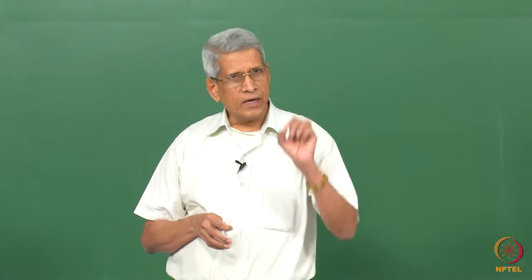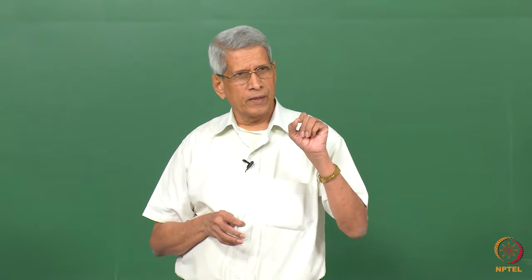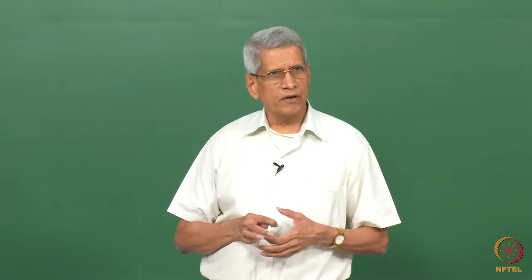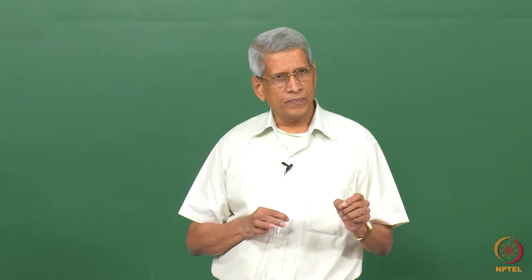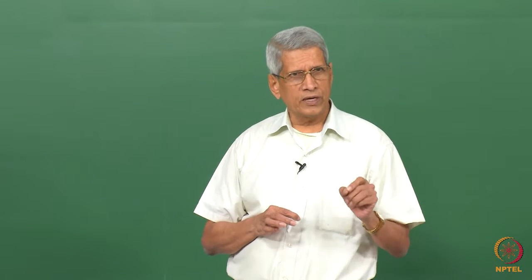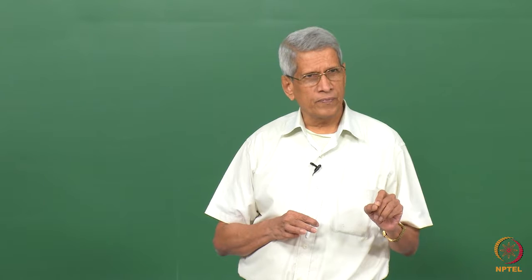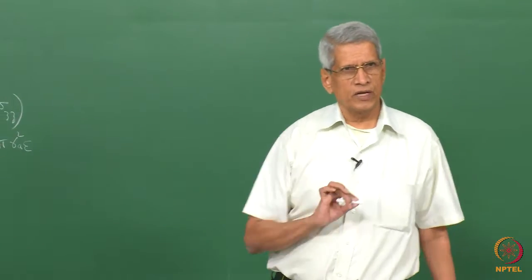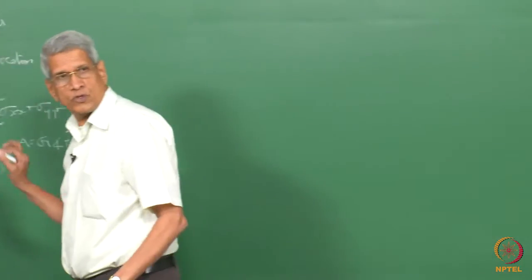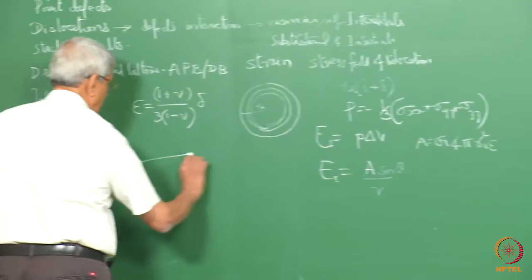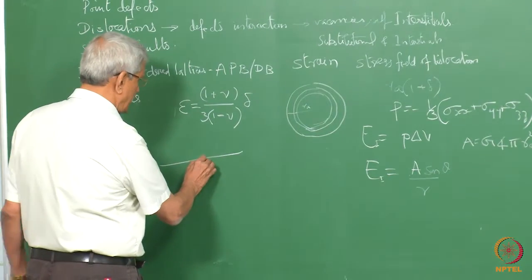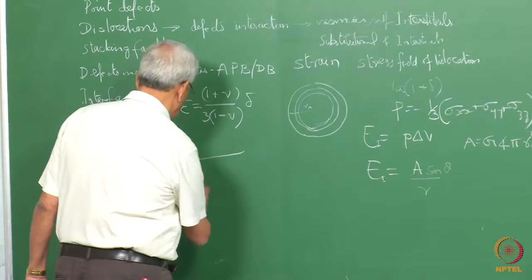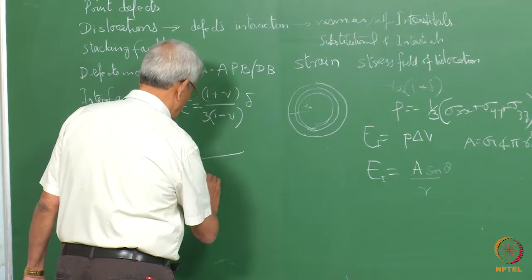Here we had calculated the energy, but the other aspect of this interaction of vacancy with a dislocation we have already considered earlier. When a vacancy interacts with a dislocation, it introduces a jog into the material, right? When it comes and gets attached, it will be shifting locally, and a jog will be created in the region where it has come.